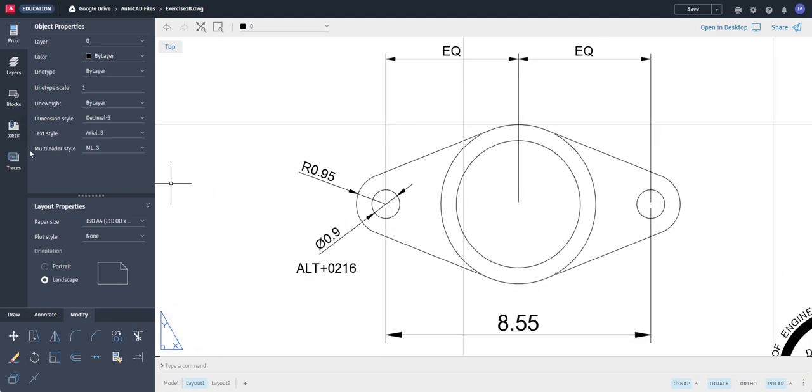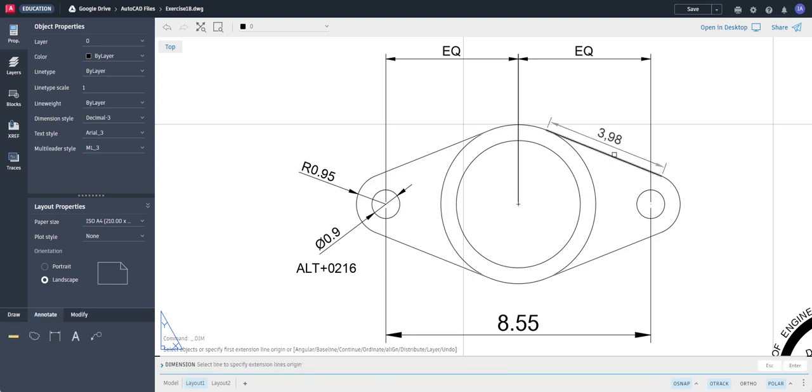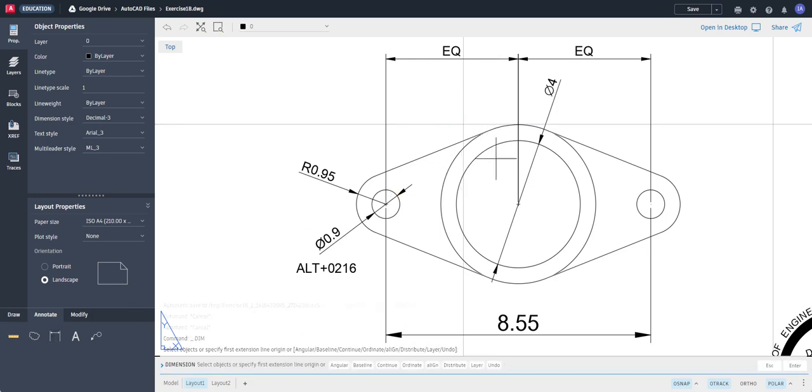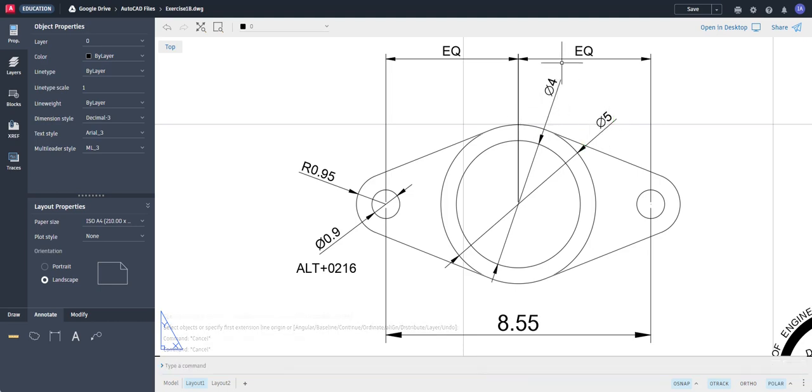You're going to put and annotate the diameter of this circle. Okay, like that, and then do the same thing over here. Diameter, oops, dimension, and then let's put it here, and then drag outside. Okay, sometimes it won't put it in decimal because it's just zeros anyway.